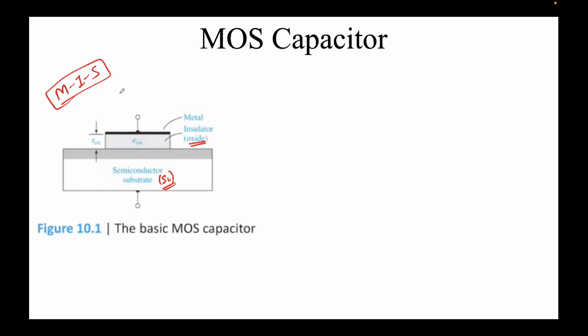You can see these are two terminal devices. Usually what we do is we ground the semiconductor terminal, and you can clearly understand it will be a Schottky contact here, because this wire has to be, you see this black dot over here, a Schottky contact essentially. We see two types of Schottky contacts, rectifying and non-rectifying, if you recall. The other terminal is here, which I will be referring to as gate, or G. This is the terminology that I'll be using throughout this session.